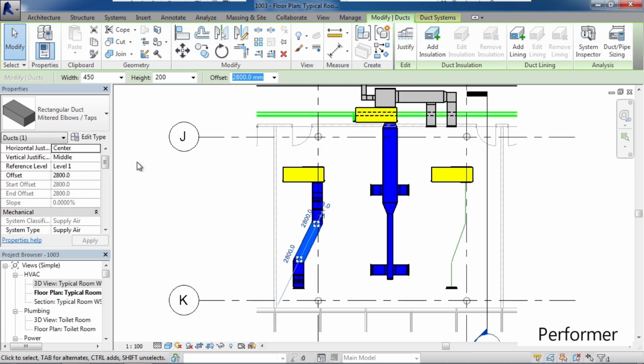We looked at the settings for the duct placeholder, offset values from the finished floor, also the differences between the duct itself and a regular duct, meaning justification and lack of insulation or lining values in the placeholder duct. And lastly, we talked or showed how you can actually convert a placeholder duct to a regular duct.